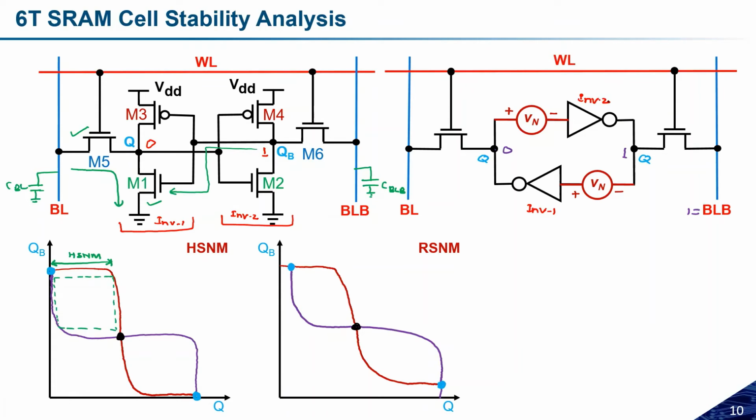So the simulation setup for the write noise margin, yeah, one more important thing, let us try to change it. Suppose the characteristics is something like this, and if we are trying to apply some voltage, if there is some mismatch here, let us assume the brown one is due to inverter number 2.